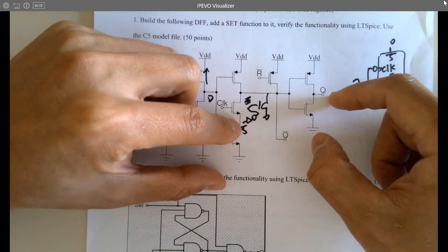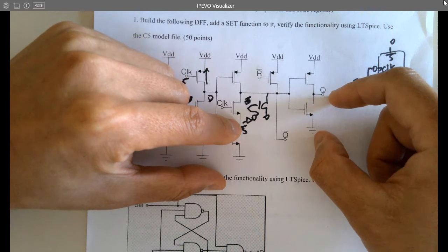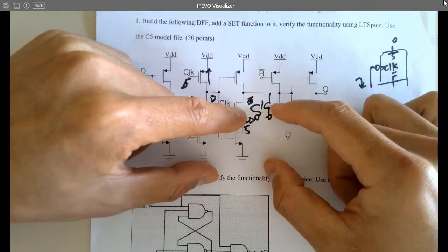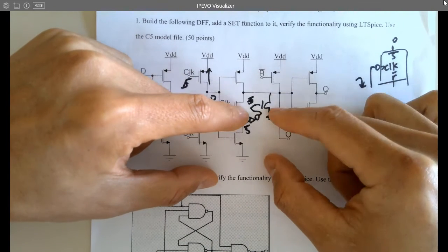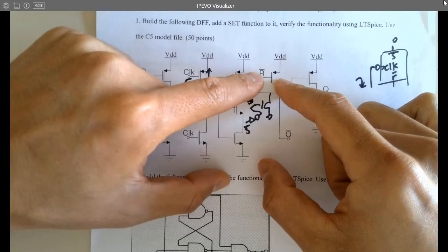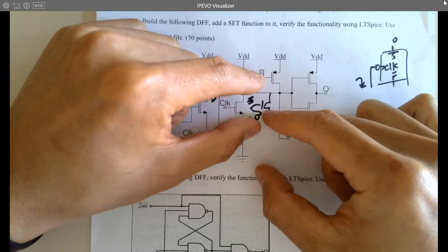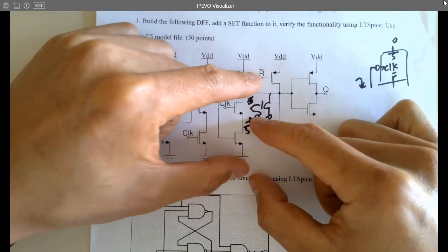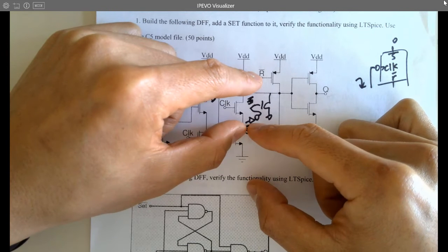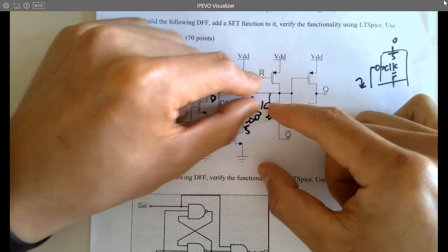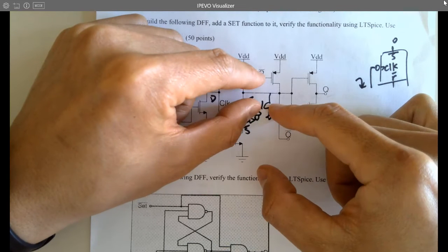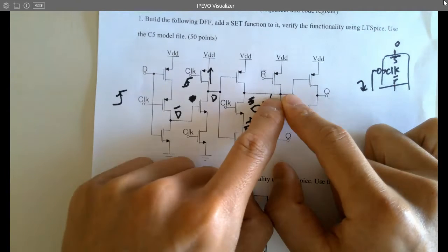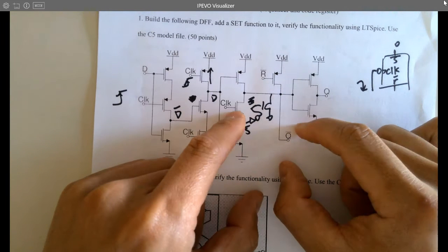0 active, yep. One thing you need to know, because this is one of the homework assignments: if you build a circuit, it may not work for the set and reset, because if you use a normal transistor width, it probably won't work. So you need a stronger PMOS and NMOS to make it work. The inverter is probably fine, but for these pull up and pull down transistors, you need them to be strong to make it happen, because there is so much parasitic capacitance.